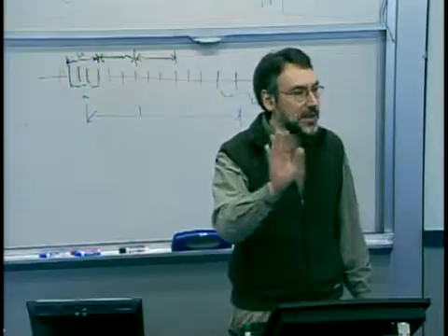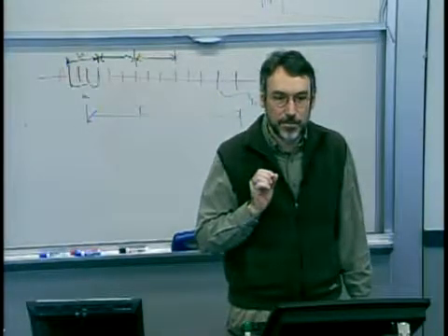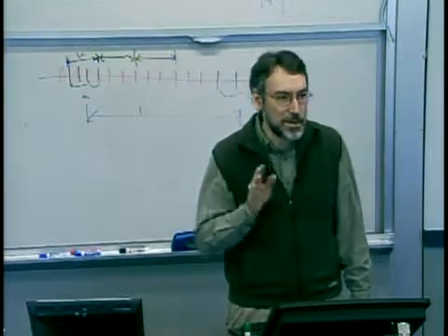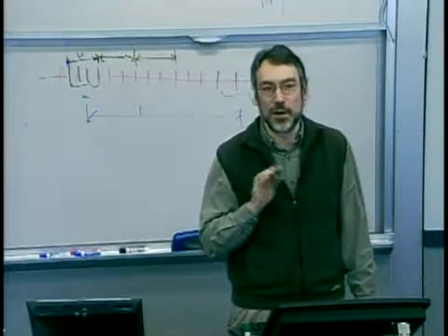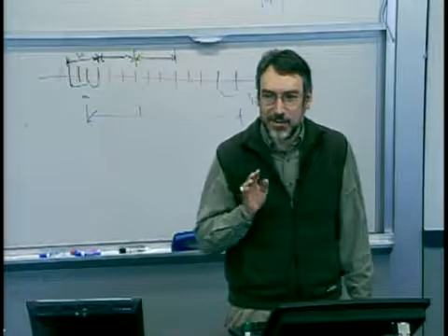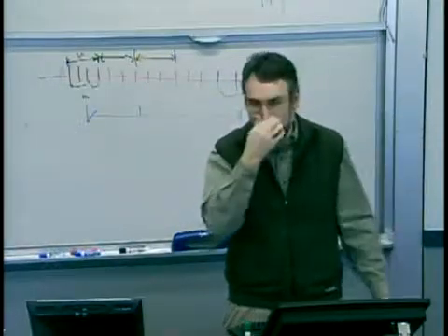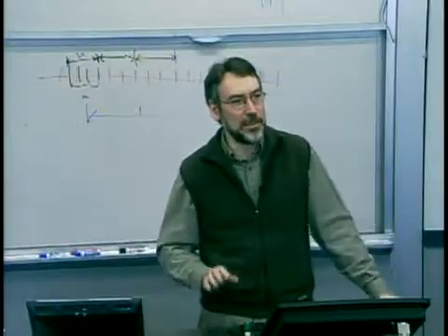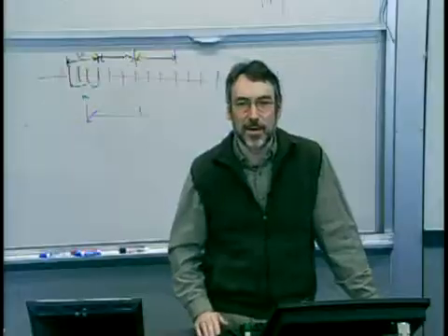By itself, you can't really know what your CP and CPK are. I would be cautious about assuming your spec limits are anywhere near your control limits. Don't assume your spec limits are plus minus 3 sigma. You're falling into the trap of assuming a CP or CPK of 1 process, which is not often the case.